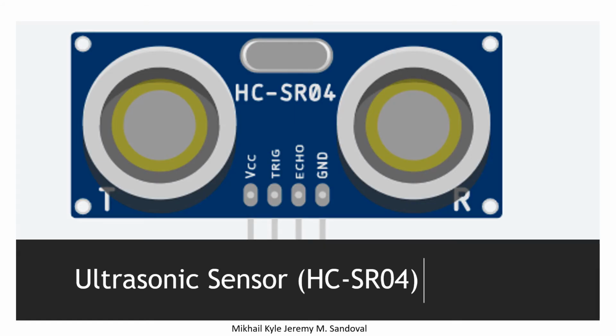The ultrasonic sensor that we used is the HC-SR04. This type of sensor is an electronic device that measures the distance of a target object, which in this case is the human body, by emitting ultrasonic sound waves and converting the sound into an electrical signal so that the microcontroller will understand the signal that will be transmitted to it.